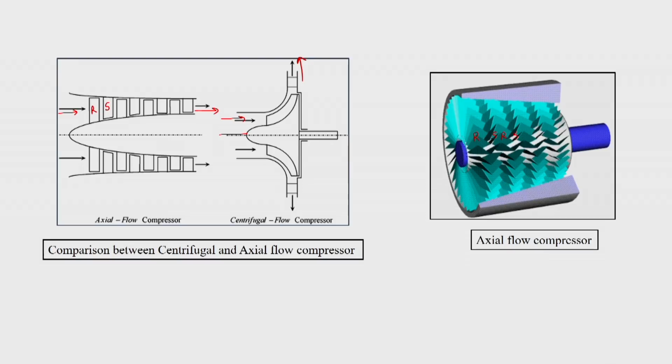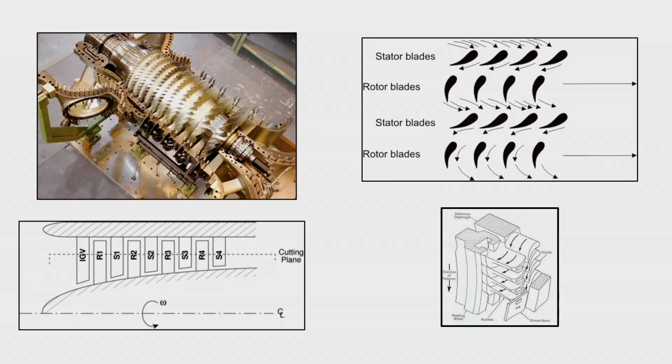That is how we considered two mutually orthogonal planes for drawing inlet and outlet velocity triangles, and there can be three types of outlet triangles depending upon the blade shapes. But here we have rotor and stator both, with the possibility of flow going axially.